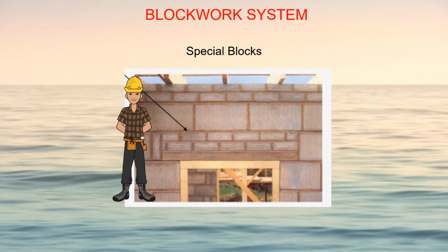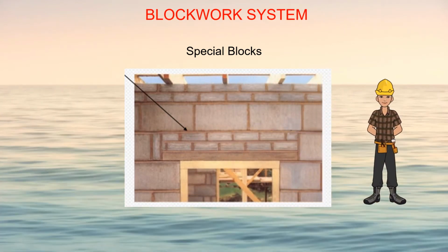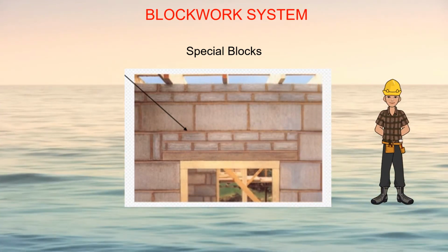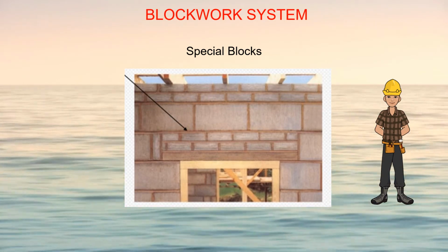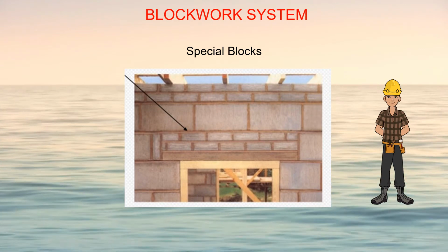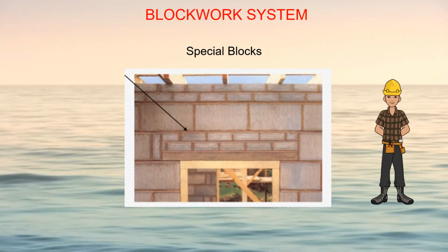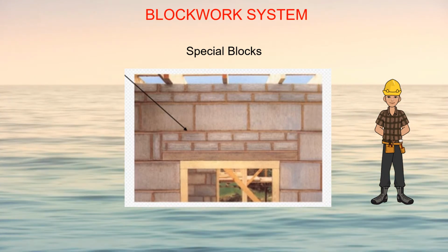To maintain bond within a wall, it may be necessary to use either coursing bricks or blocks. These can be cut from a whole block or special blocks manufactured to those sizes. These blocks are built into the walling adjunctions and over openings in the wall.